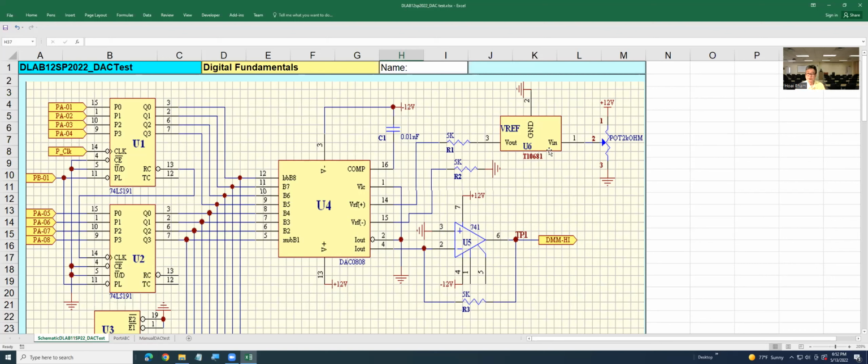Adjust connect to pin number 3. Adjust the pot in here until pin number 3 equals 10, so you get 10 volts here. If they ground pin 14 inside, you get 2 milliamps. Okay? And pin number 3 connect to minus 12 volt.